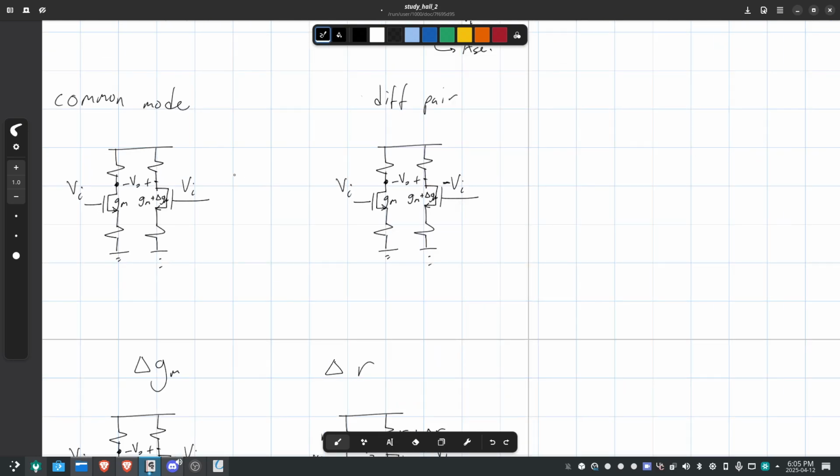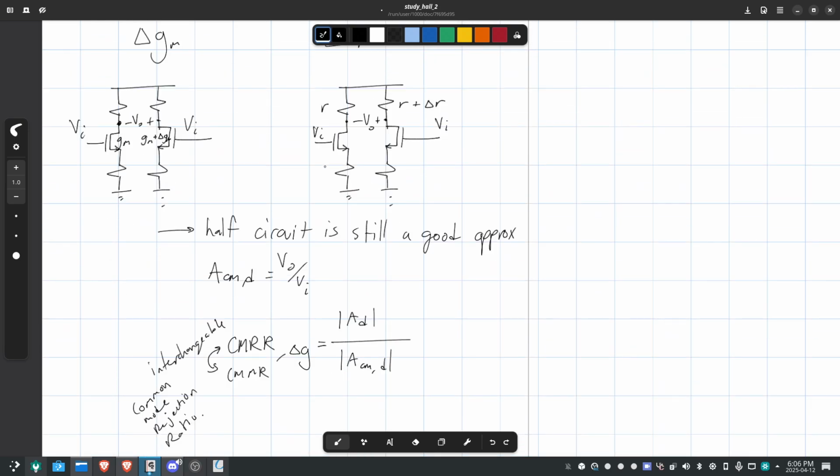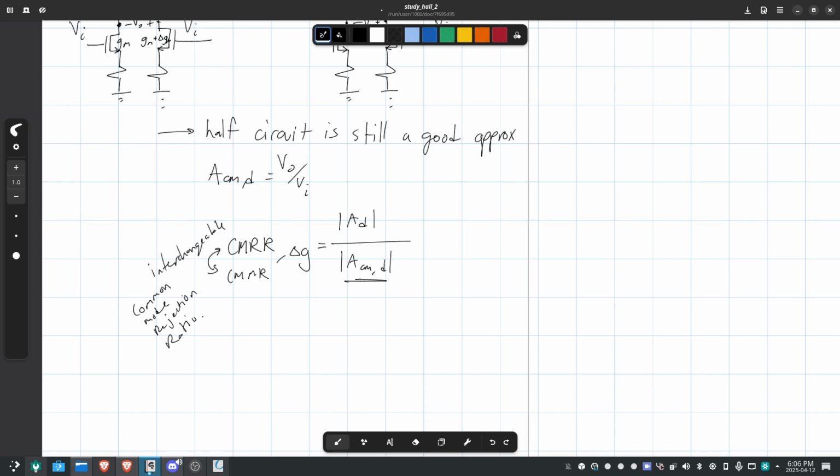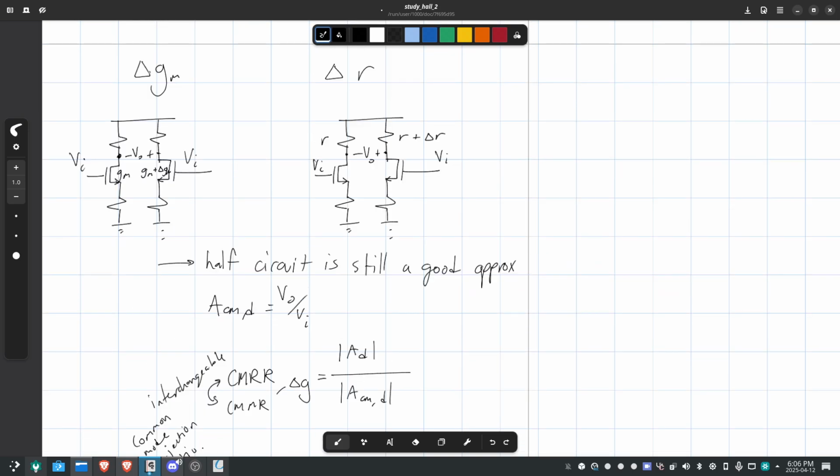We use this to simulate what happens if a little bit of noise gets in, right? If both gates get some voltage, the same amount, we call that common mode. So if we're working in common mode and there's a minor error in resistance in one side, what is the amplification gain? If these two circuits were completely, absolutely identical, it would be 0, right? Because if you get plus 0.1 volt here and plus 0.1 volt here, the difference in VO, again, is going to be 0.